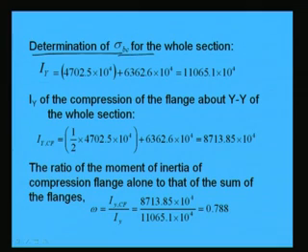We will determine the sigma BC for the whole section. Now, this is a new thing which we have not discussed earlier, means we have not done any example on how to find out sigma BC. Why? Because not only is the beam unrestrained against its lateral direction, but the cross section of the beam is also not symmetric. So, because of that we have to find out from the formulas, right. In case of equal flanges with an unrestrained beam, we have the tabular results in the IS code in table 6.1 to 6.1a to 6.1f, but in this case we have to find out.